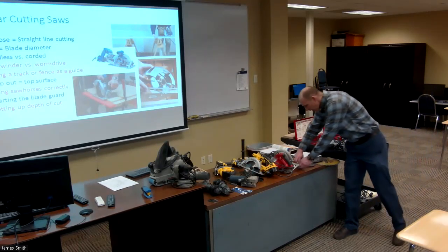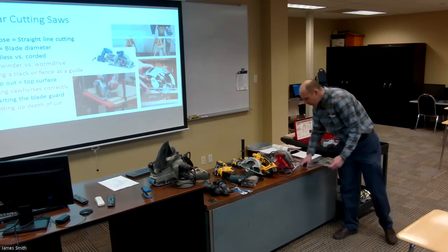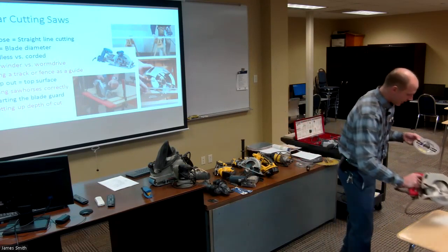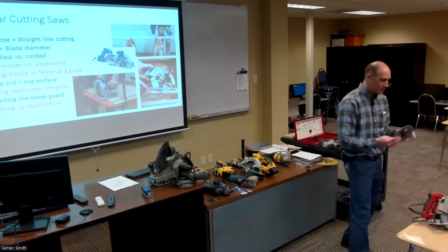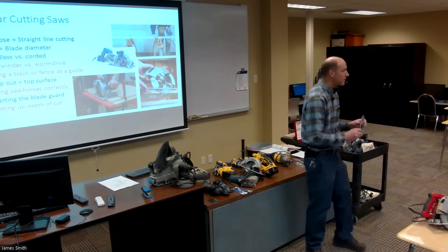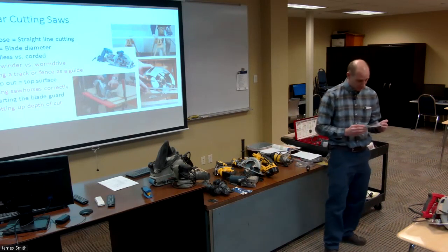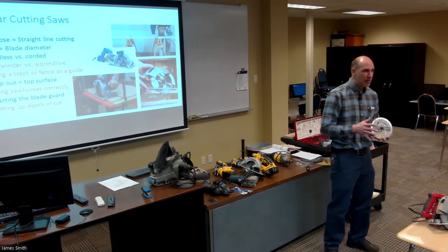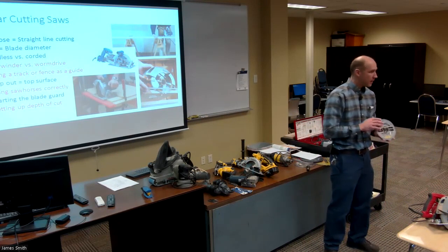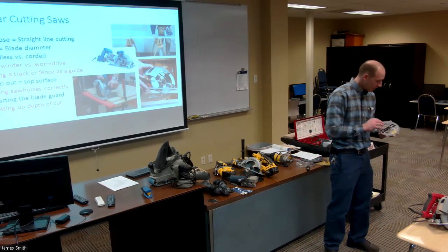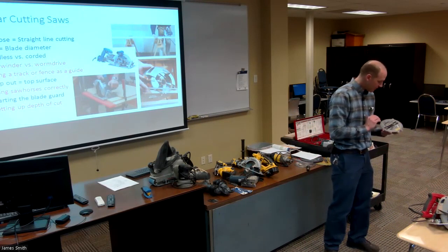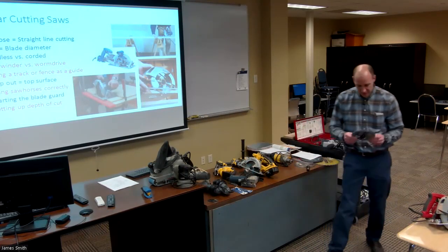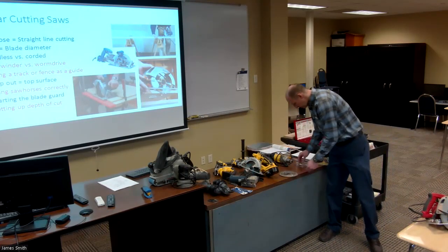Generally, your circular saws, your portable ones like this one here, are going to take a blade that looks like this, okay? And there's different types of blades. So this is a 60-tooth blade. This would be more for if you're cutting plywood, right? Or cutting something that needs to have a better looking finish, right? Cross cutting, that sort of thing. It's got small teeth, small gullets. It's got carbide teeth, so it'll stay sharp for longer. And so that's what these little blades are for.